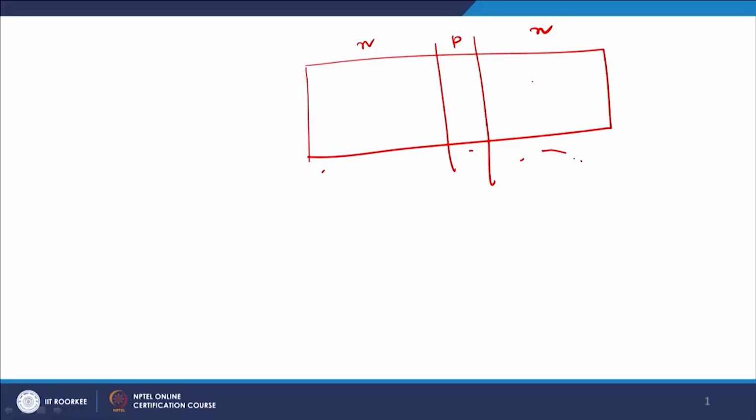So what we will be looking at is the drift in the base region. If you look at this equation, I_nx, the first part, this is the total current because of the charge carriers in the region. I have got an NPN transistor, and within that, as I discussed, N has got the largest doping and highest area, P has got the minimum doping and minimum area, and the collector has got relatively moderate doping.